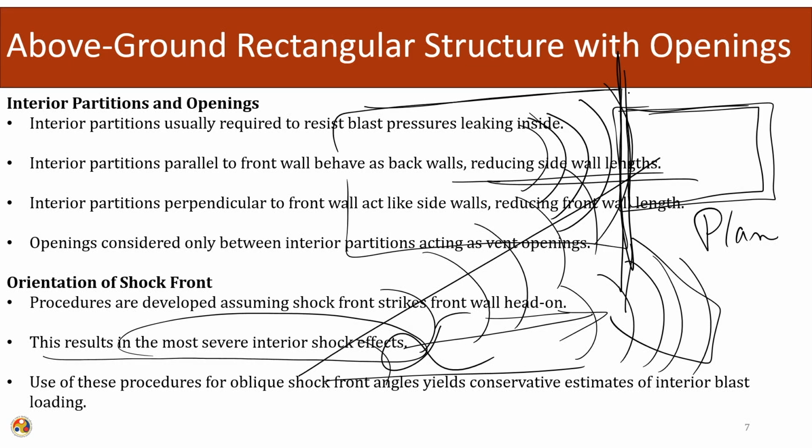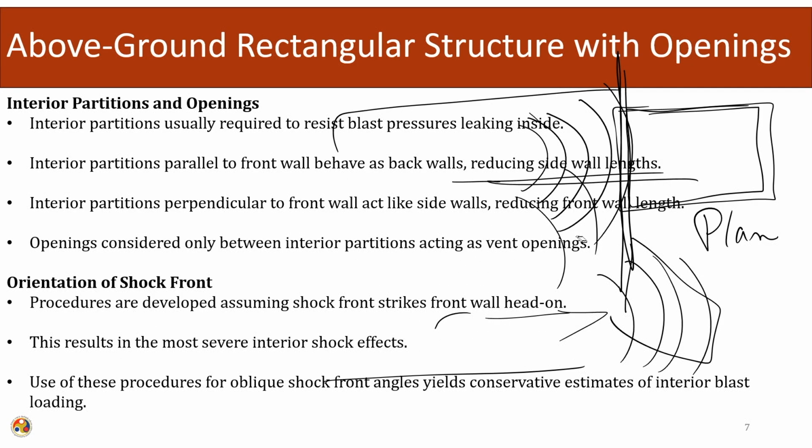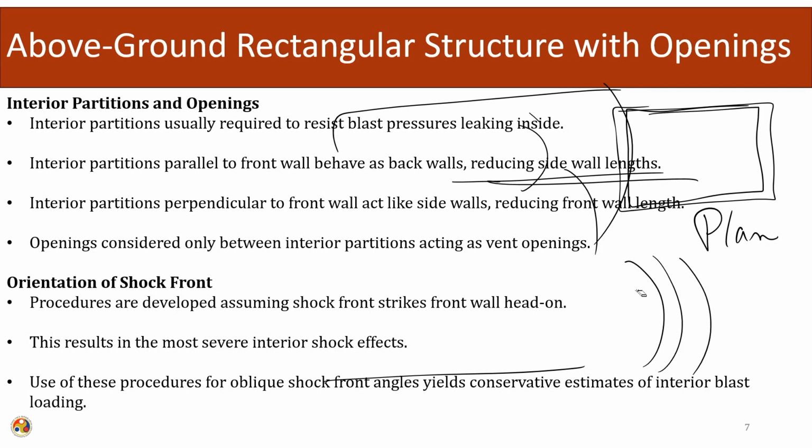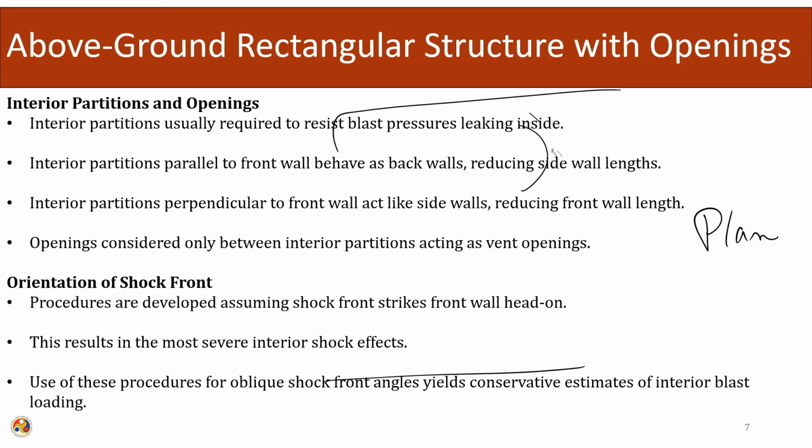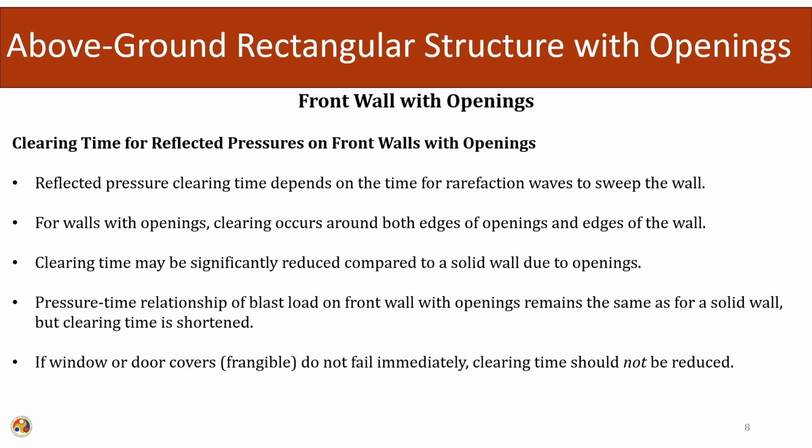So this will give us a conservative effect, when in reality the shock front is supposed to hit at an angle. So we will be over safe in our design. Moving ahead: front wall with openings. Clearing time for reflected pressure on the front wall with openings.